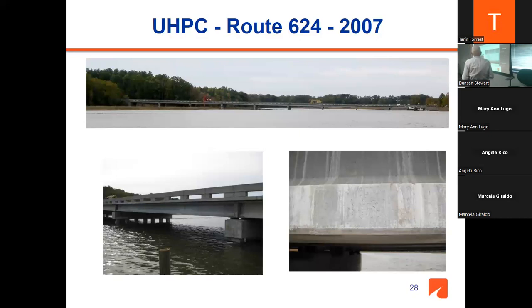Okay, but does that mean VDOT doesn't use ultra high performance concrete? No, that's not true. This bridge, from 2007, has 10 spans near Tappahannock. In one of the spans we put ultra high performance concrete. 5 beams there, all made with ultra high performance. The beam itself? The 5 beams totally UHPC. So we have a good history with ultra high performance in the state.